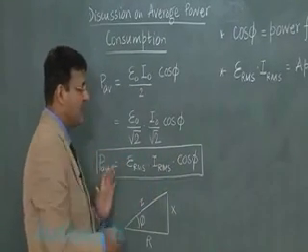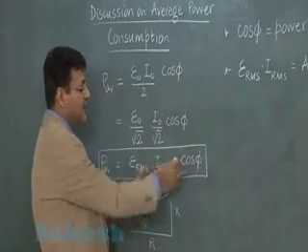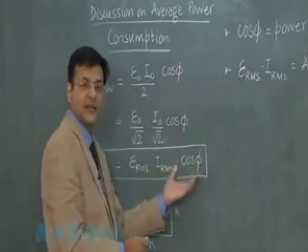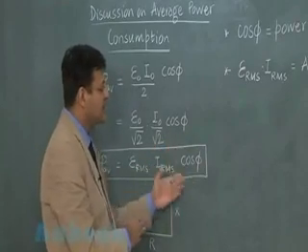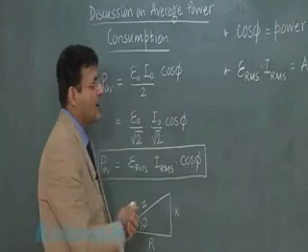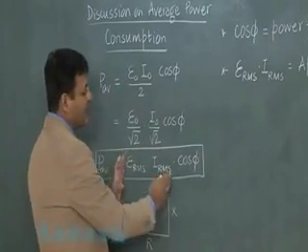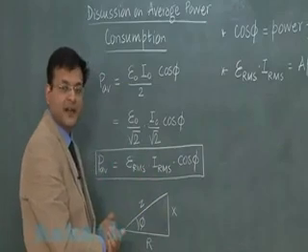In the expression for average power, there is not only the role of ERMS and IRMS, there is one more term, cos phi, which also plays a role. That is why this is being called power factor, and this much term is called apparent power. So you should understand that average power is apparent power multiplied by the power factor.